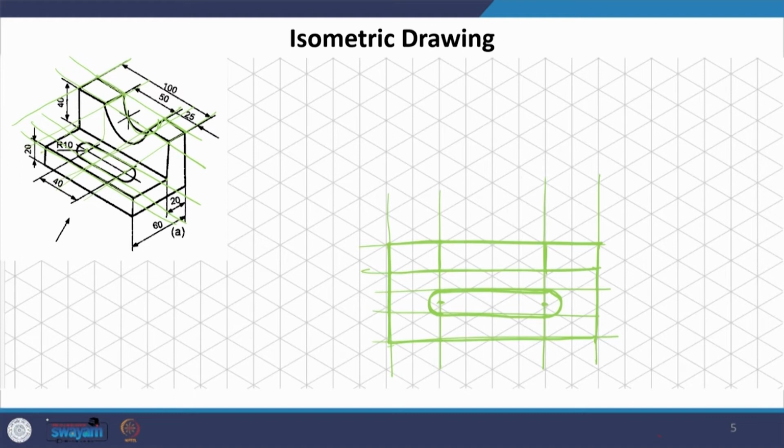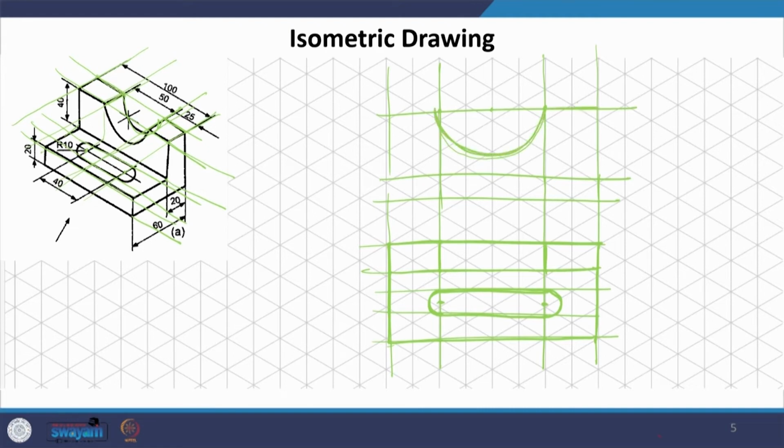Now, take it back to the elevation. So, these lines will remain the same in elevation, okay. So, we just take these lines in the elevation, okay. And now, we will just draw the horizontal lines. So, at 1, 2 and 3, they are just 3 lines. Now, look at it in the front, and what do we get? We get this edge here, this edge here, and we have to identify where the center for this one is, and we draw a semicircle, which is what we are getting in the object. So, we get this part, okay.